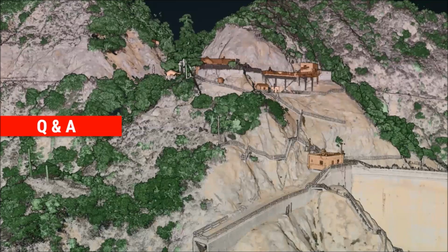At that point, you've got your beautiful point cloud, but you want products coming out of it. I use LAStools a lot. I'm starting to explore some of the options in Spatial Explorer as well to get DEMs. But what I've been using for a while is LAStools, and we've got workflows in there. It's fast. And then we have a lot of custom software in order to get some of those more complicated products that I was describing. That's all custom stuff in-house at the Gator Eye team.